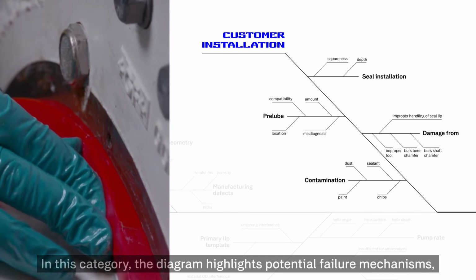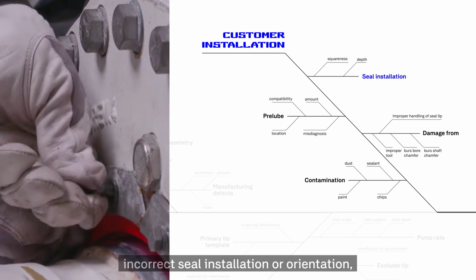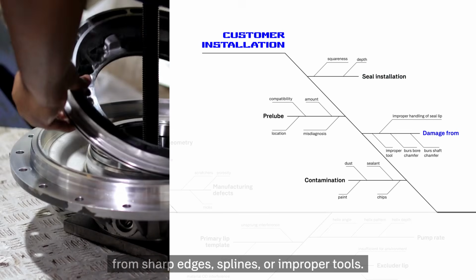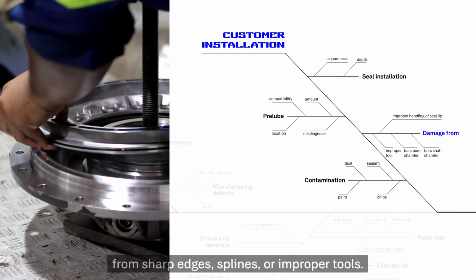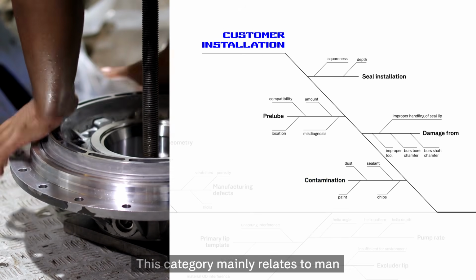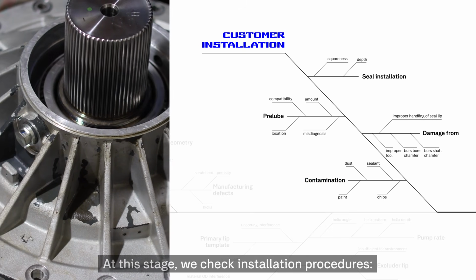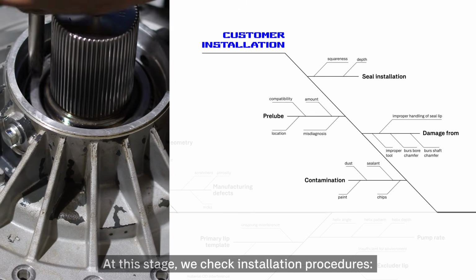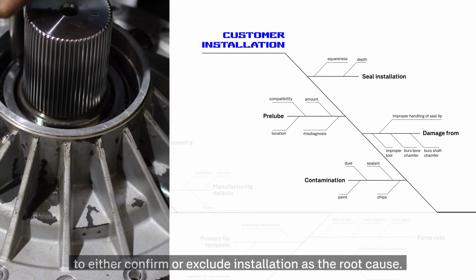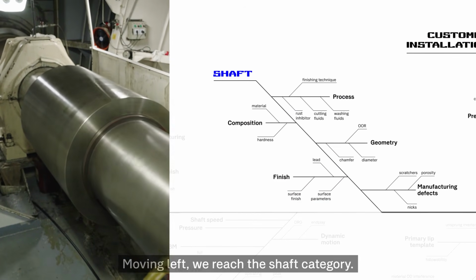In this category, the diagram highlights potential failure mechanisms such as incorrect seal installation or orientation, damage during installation, for example from sharp edges, splines, or improper tools, and contamination introduced during assembly. This category mainly relates to man and method in the 6M logic. At this stage, we check installation procedures, tools, handling, and visible damage to either confirm or exclude installation as the root cause. Moving left, we reach the shaft category.